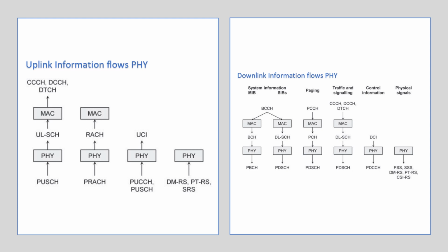The downlink control information mainly comprises scheduling commands and scheduling grants, by which the base station alerts the mobile to a forthcoming downlink transmission on the PDSCH and gives it resources for an uplink transmission on the PUSCH. There are three main types of uplink control information: the hybrid ARQ acknowledgement of the base station's transmission on the PDSCH, scheduling requests if the mobile wishes to transmit on the PUSCH but does not have the resource to do so, and feedback about the nature of the downlink radio channel, known as channel state information, that is CSI. Downlink control information is delivered on the physical downlink control channel, that is PDCCH, while uplink control information is delivered on the PUSCH if the mobile is transmitting data at the same time, and on the PUCCH otherwise.